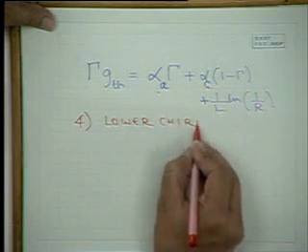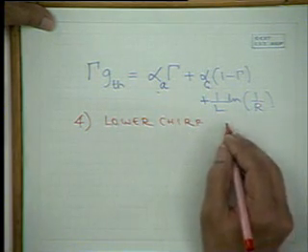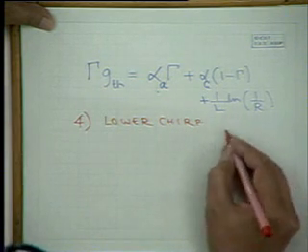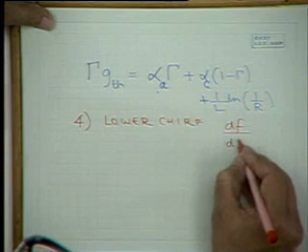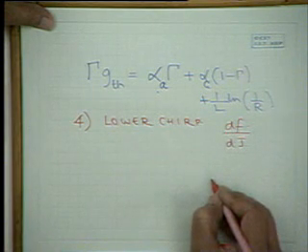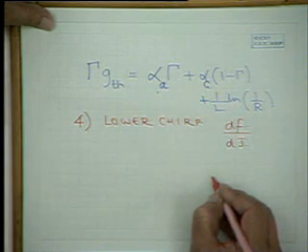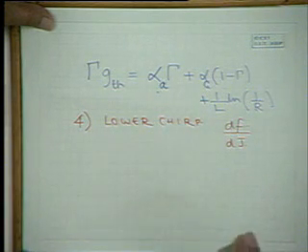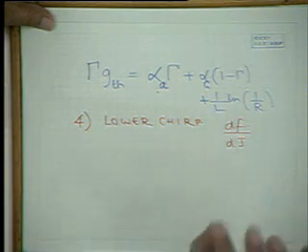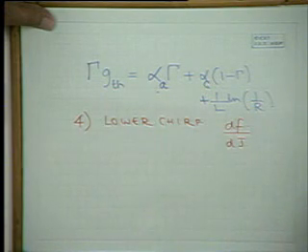And another advantage for systems applications that I could mention is that there is lower chirp, that is the variation of frequency with current, injection current, or with temperature. You want a laser to work, no matter at low level or high level, so the frequency should not shift.